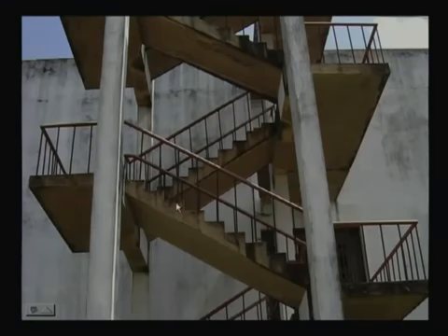Here there is one step. You can see all the steps. So you have to consider the dead load of the steps also, the weight of the steps. And this is what is called the waist slab. So how to design this one? The first one we described had steps one after another, but here we are assuming these steps are supported by this slab. So that means I can design that slab.